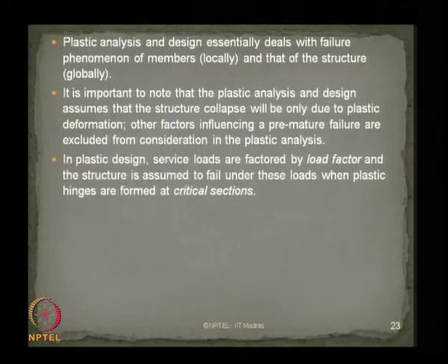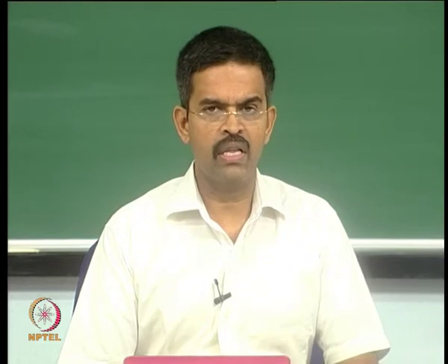In plastic design, service loads acting on the member are factored, basically multiplied by a load factor, and the member is assumed to fail under these loads when plastic hinges are formed at critical sections. Ladies and gentlemen, in a plastic analysis you must understand what we mean by critical sections.